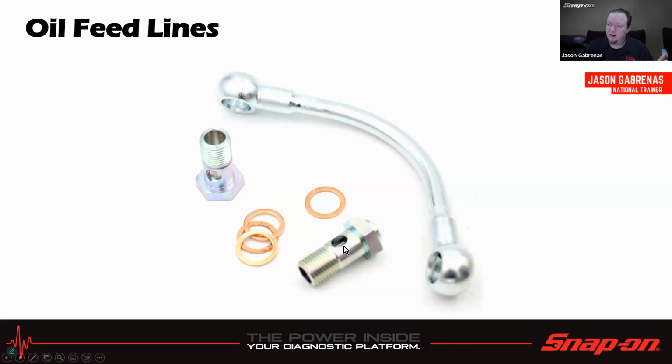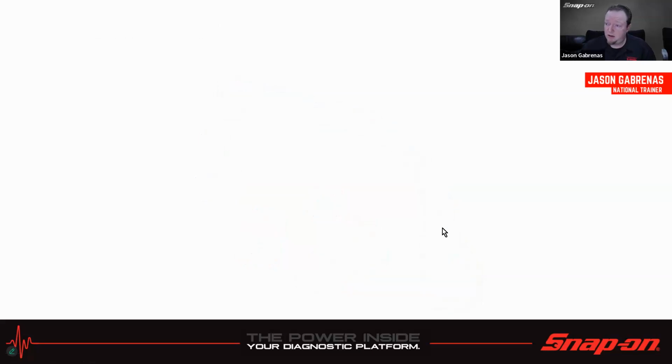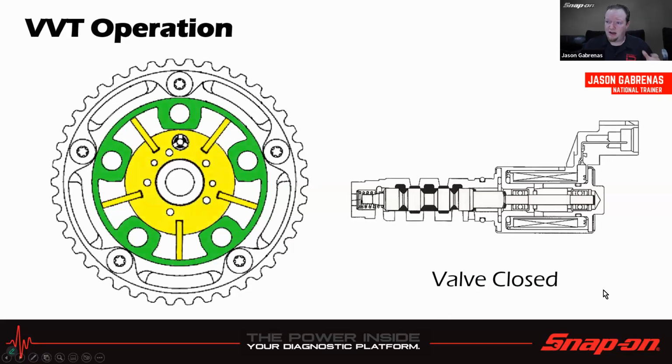So that can be a maintenance issue and can cause failure. It could be a failure point right there. And then, of course, when you replace them, they are banjo bolts, so you want to replace the washers as well. So let's look at the operation here.